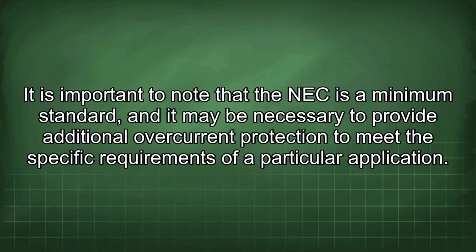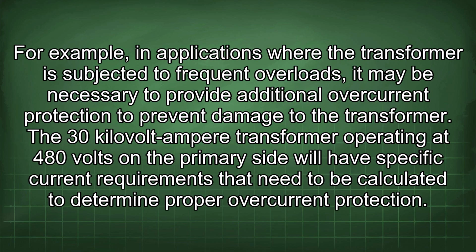It is important to note that the NEC is a minimum standard, and it may be necessary to provide additional overcurrent protection to meet the specific requirements of a particular application. For example, in applications where the transformer is subjected to frequent overloads, it may be necessary to provide additional overcurrent protection to prevent damage to the transformer.